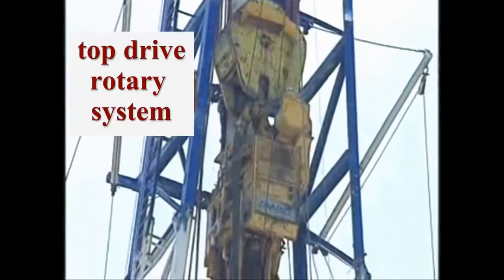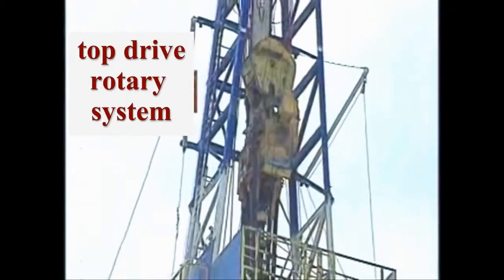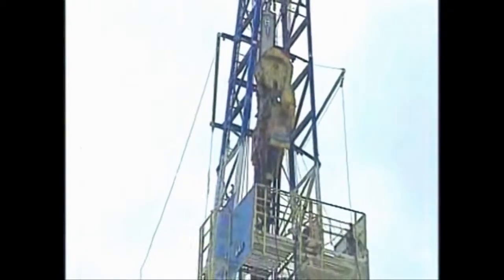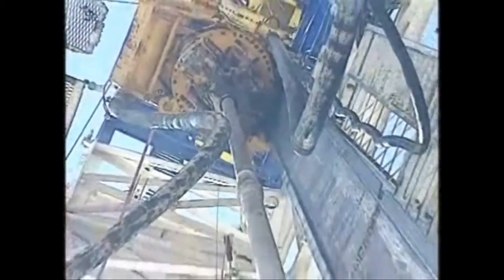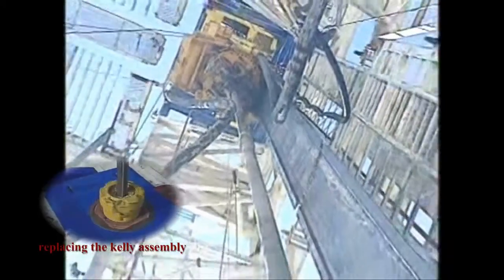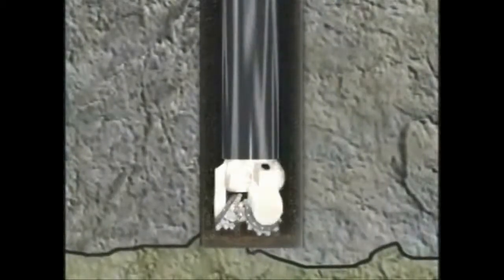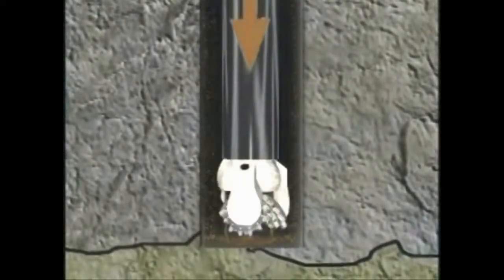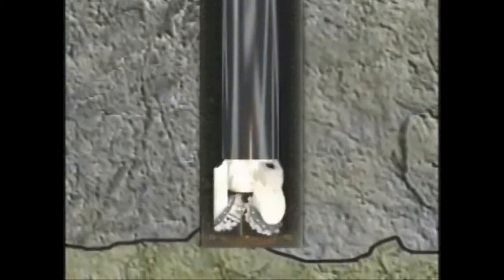Another, newer type of rotating system is called the top drive. The drive shaft, with its powerful hydraulic motor, screws directly into the drill stem. Replacing the Kelly bushing and the rotary table, the top drive suspends and rotates the drill stem. The drilling fluid flows through the top drive, down through the drill stem, to the bit below, just like with the Kelly assembly.